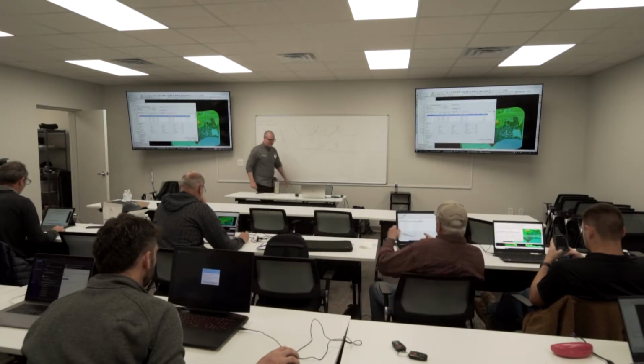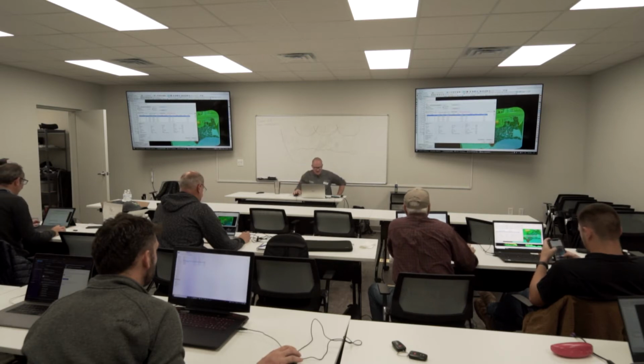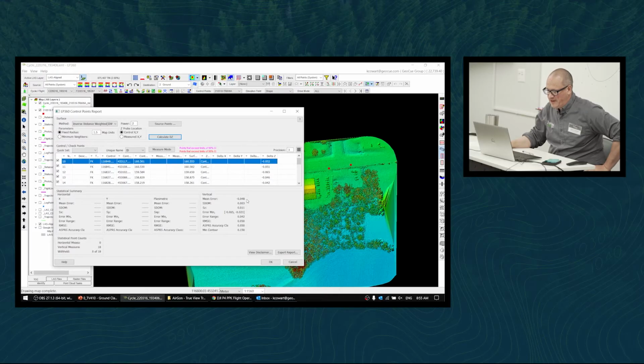All right, so this is a good training data set to show off sort of debiasing. You can see that our mean error here is about negative 4.8 centimeters. I'm not going to get into the statistics of how this works, but if your SDOM, or the standard deviation of your mean, is a very small value and nowhere near close to your mean error, then that means that there's a consistency of that bias. They can be averaged down to about 4.8 centimeters. So because of that, you can justify debiasing this data set.